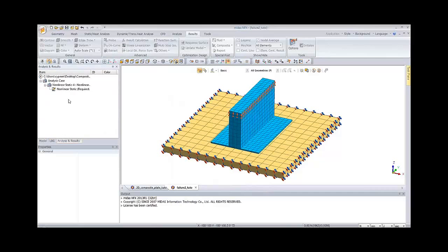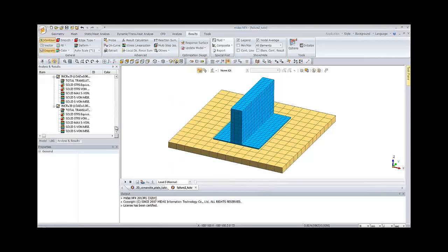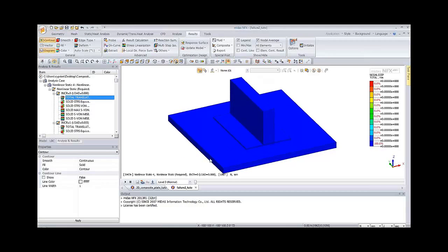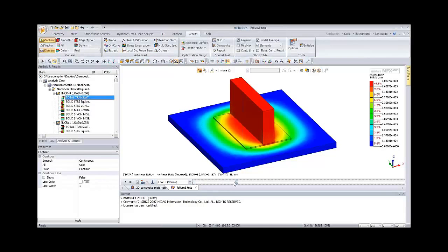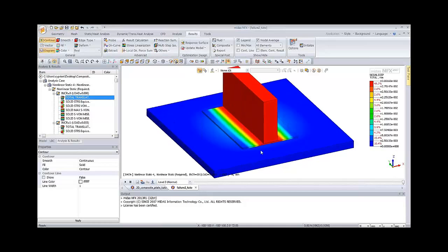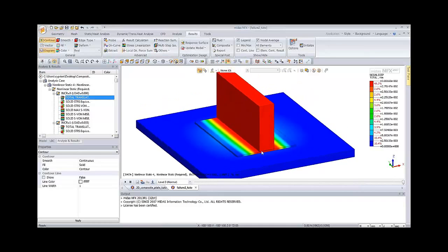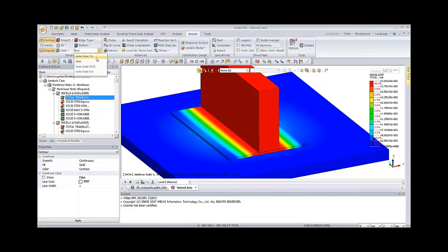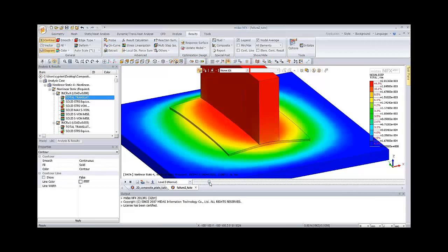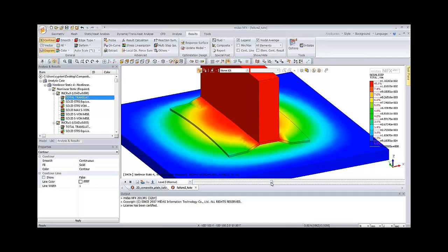So first of all, the displacement. I will set it first to real, so it gives me something like that. So this is a nonlinear static analysis. When I go through the steps, you see the form of the behavior is changing. It's difficult to see, so I will increase the scale and come back to the beginning. So you see from there, when the analysis continues, the contact is breaking with the plate. And finally I have something like that. So there's a space between the two.